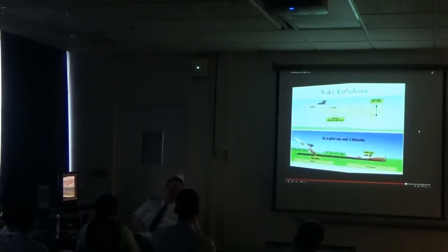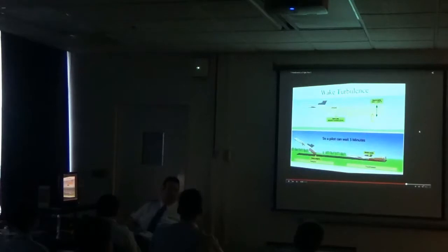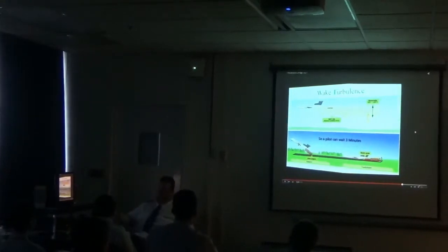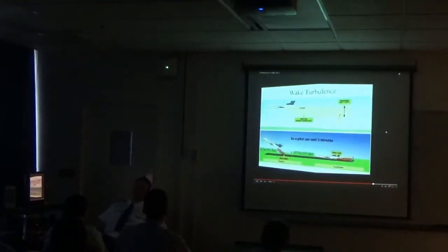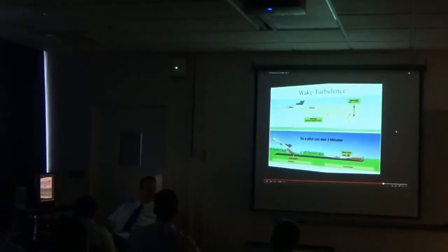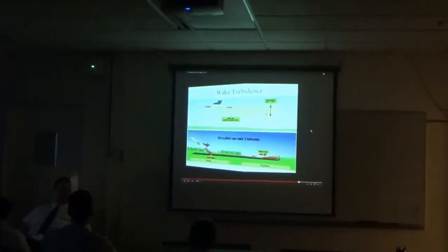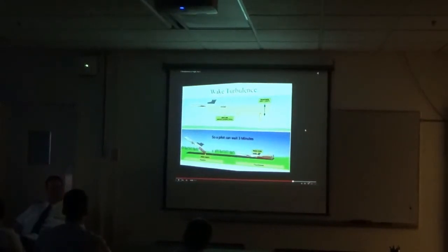I'm sure some of you have probably looked on YouTube. You've seen a video of the jet engine, and you see the car driving down and getting knocked away. That is less likely to happen if you're away from the jet, because the thrust usually dissipates quicker. It's the wingtip vortices, that generation of slow and fast wind coming together and creating that vortex, that is a bigger danger than the thrust of the aircraft. And even with a small propeller engine, I've stood behind small single engine aircraft while taxiing or increasing thrust, and it kind of blows on you a bit, but it dissipates rather fast, so it's a bit different. Any other questions?